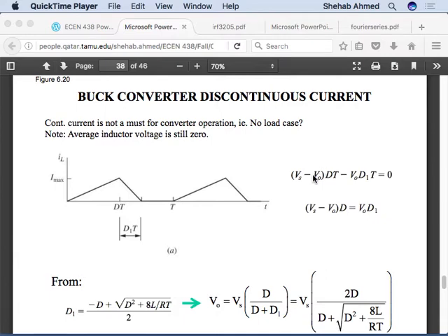The area is Vs minus V input minus V output, the voltage across the inductor when the switch is on, plus the other area, which happens to be negative: negative V output times the duty cycle D1, which we don't know the value of, multiplied by the switching period, right? So this is called volt-second balance. From the volt-second balance, we found the relationship. Then in the textbook, there was a derivation for this D1 duty ratio that we don't know, in terms of everything else that we know about, right?